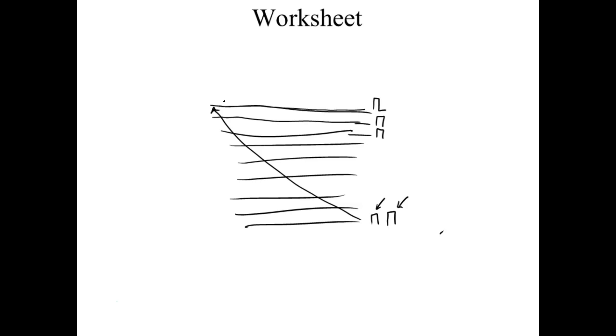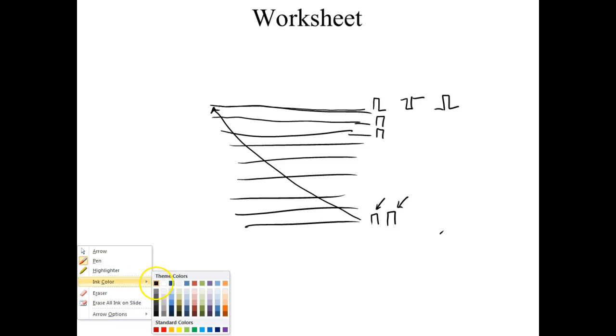But what they had was, when they first came out with the video between the computers, some monitors looked at sync pulses that were like this. Some monitors looked at sync pulses that were like that. So we had to go into our video card, and there was a little switch on it. If we plugged it in and plugged the monitor to it and it came up out of sync, then it probably told us what? That we needed to invert the sync pulses. Now over time this has disappeared, so we had to come up with some way that we could have what we call programmable inverters.